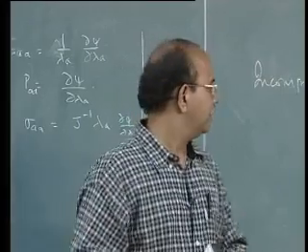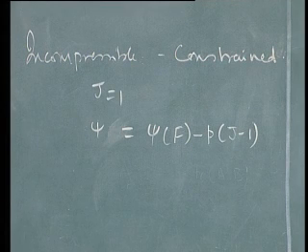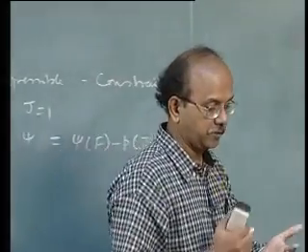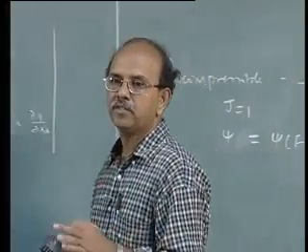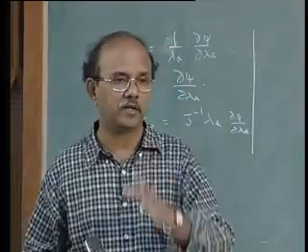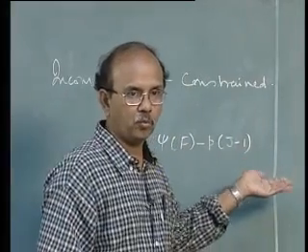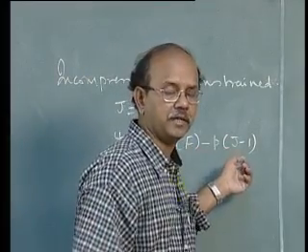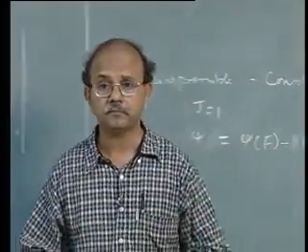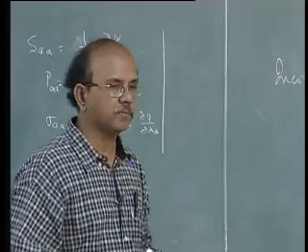and then determine the Lagrangian multiplier as well. So what it really means is that this p, which is a scalar quantity, though identified with respect to pressure, can be determined only by means of kinematic conditions, or in other words, boundary conditions. This is not supposed to do any work. It's a non-working scalar quantity, which comes because of the condition that J should be equal to 1, and this has to be determined. We'll do a small problem later.